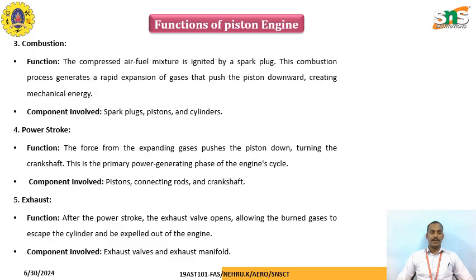The next part is combustion. The compressed air-fuel mixture is ignited by a spark plug. This combustion process generates a rapid expansion of gases that push the piston downward, creating mechanical energy. Components involved are spark plug, piston and cylinders.